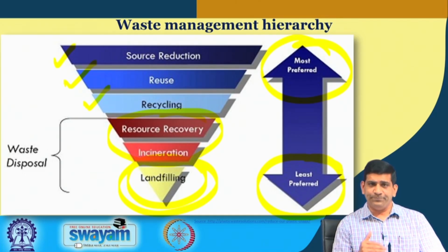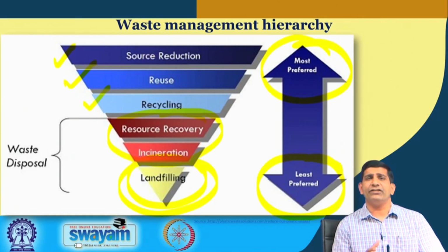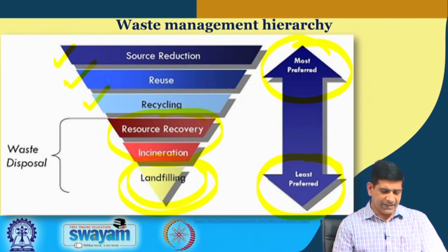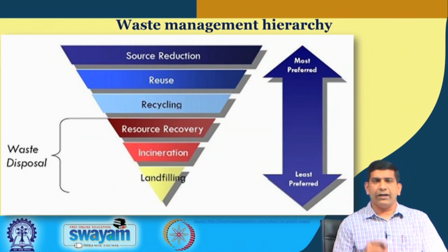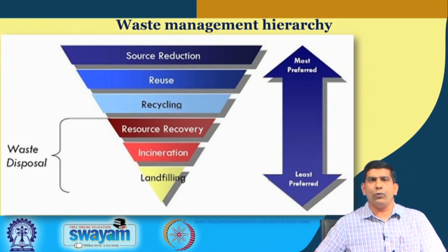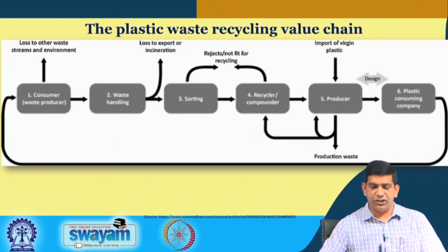Only thing is that when you have plastic in the incineration plant, you have to be careful about the temperature of operation of the plant to make sure you don't produce dioxins, furans, and those kinds of contaminants. That being said, let's move on. I just wanted to give you an idea of how waste is managed in general.